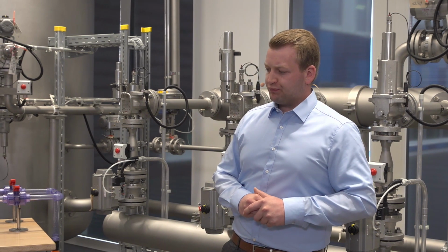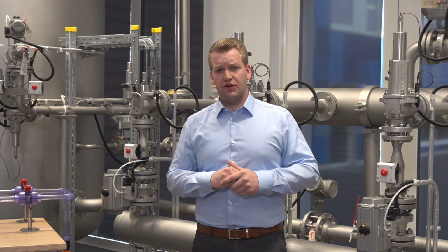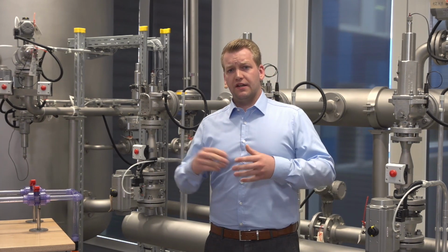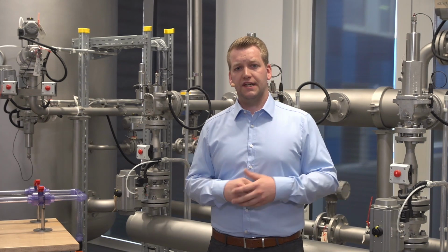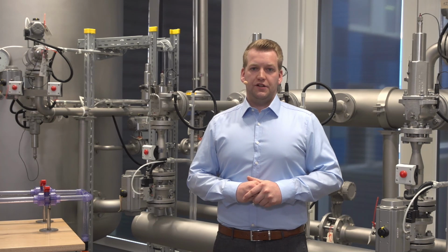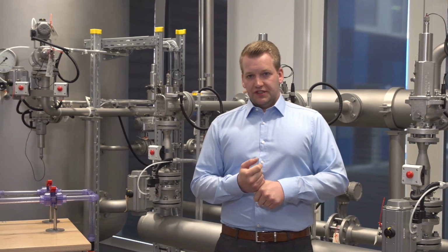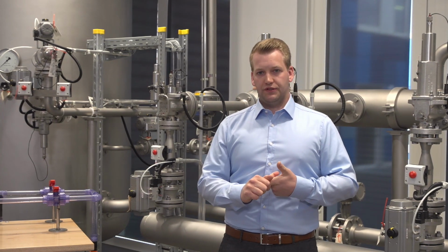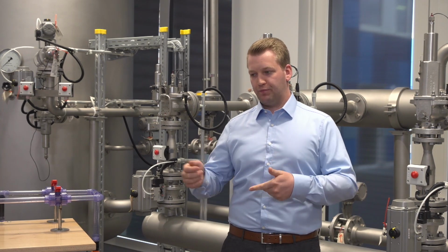And this process is limited by the rubber materials of the clean service safety valve. A typical standard limit from our side is 150 degrees for a standard rubber material. This is around 4 bar. And these are the limits here. So you heard something about the CIP process and the SIP process, sterilization in place.